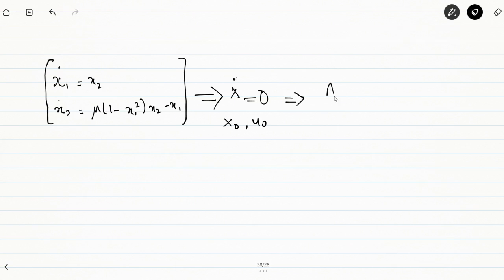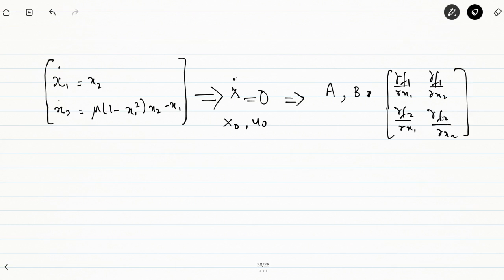After you do that you have to basically find out the matrices A and B, where A matrix is actually delta f1 by delta x1, delta f1 divided by delta x2 up to delta xn, and delta f2 divided by delta x1, delta f2 divided by delta x2। So जितने भी functions होंगे, जितने भी state variables होंगे, partial differentiation with respect to each other, and you will find out this A matrix। This A matrix is known as the Jacobian matrix, and you may be studying this in power systems in the past term also, ठीक है। You'll be finding out the Jacobian matrix in that case also, ठीक है। वहाँ पे हम basically जितनी भी power equation होगी, voltage equation होगी, we differentiate them with respect to each other and find out the Jacobian matrix for analysis of the system.